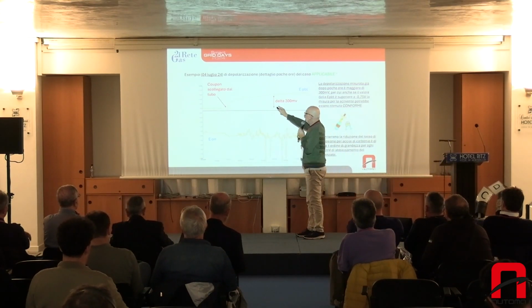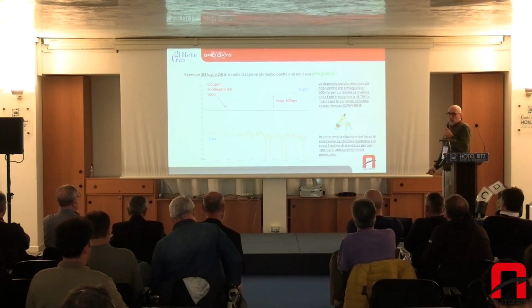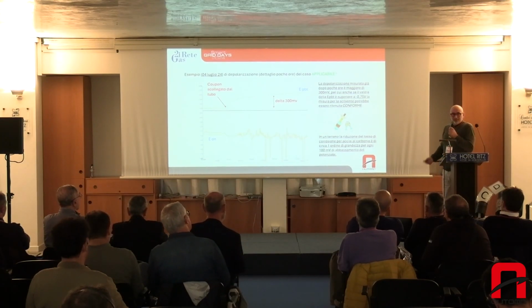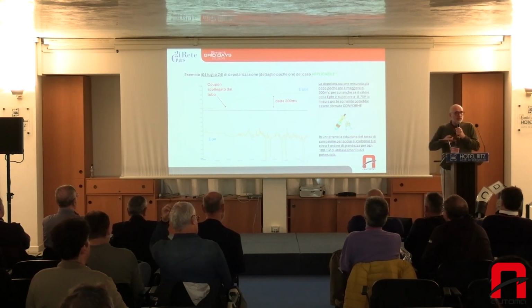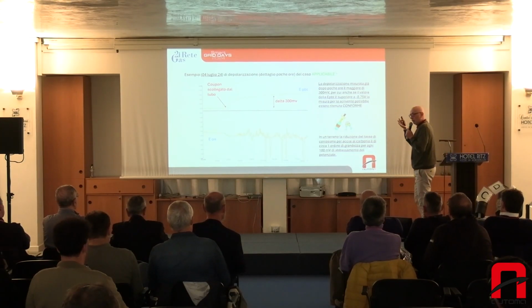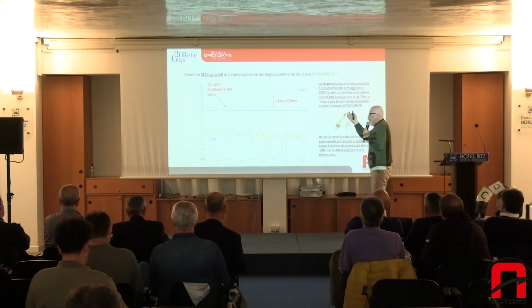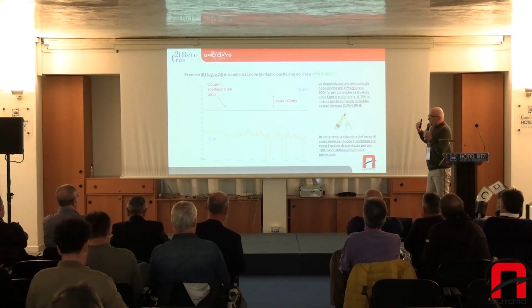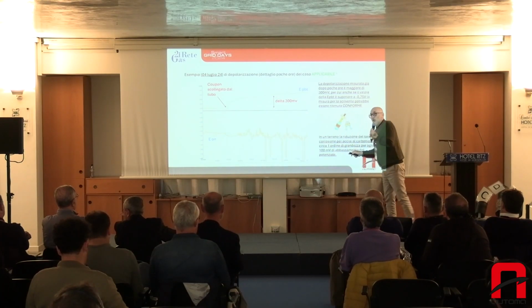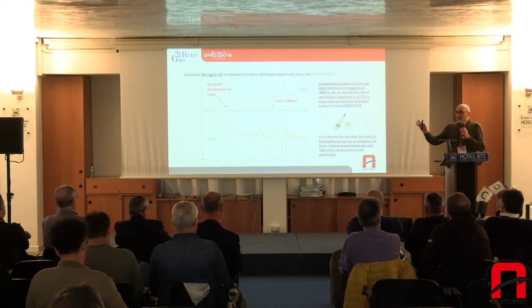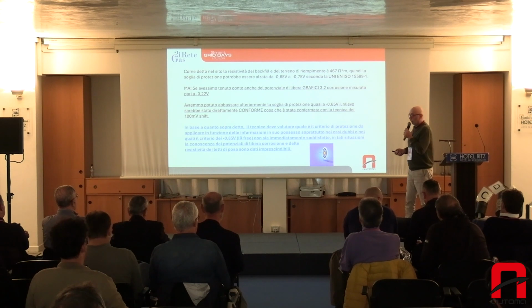Okay, I have here a 300 millivolt delta. 300 millivolt is quite stable, and it's far more than 70 millivolt. Do I have a good perception of the idea that that measurement is not really concerning? Yes. Also because every 100 millivolts increase in the protection potential, I slow down corrosion. So this measurement complies, in my opinion.